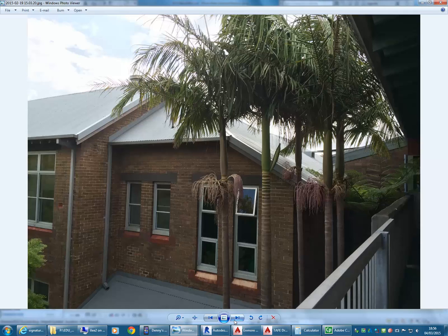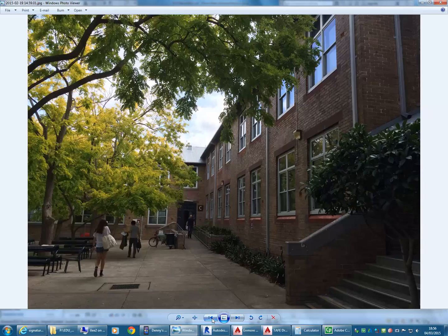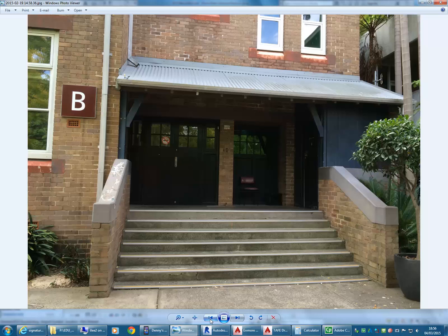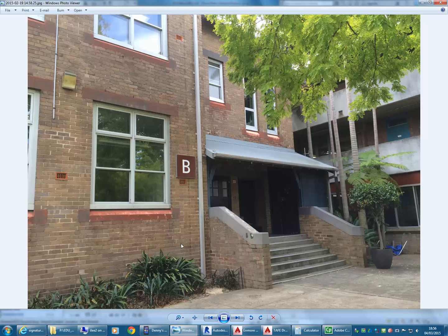So starting with those steps. So right, that's your floor level, and then you can follow that course around. And here we are. These are the photos I wanted. So that course there, you can follow it around once you get a photo from the other side, which here we are. And then from there, you know that's roughly the course of the floor height. And then counting bricks, you can work out the sill height of that window, and then just keep going up from there.